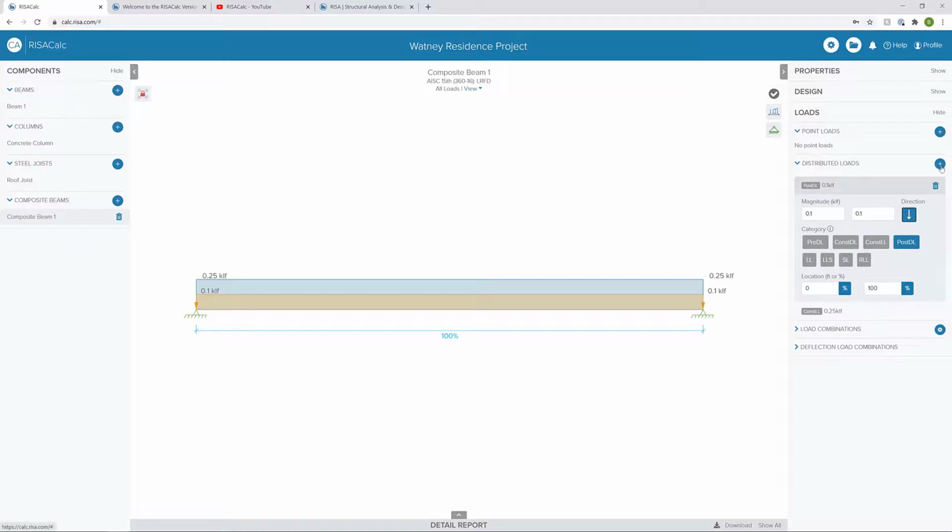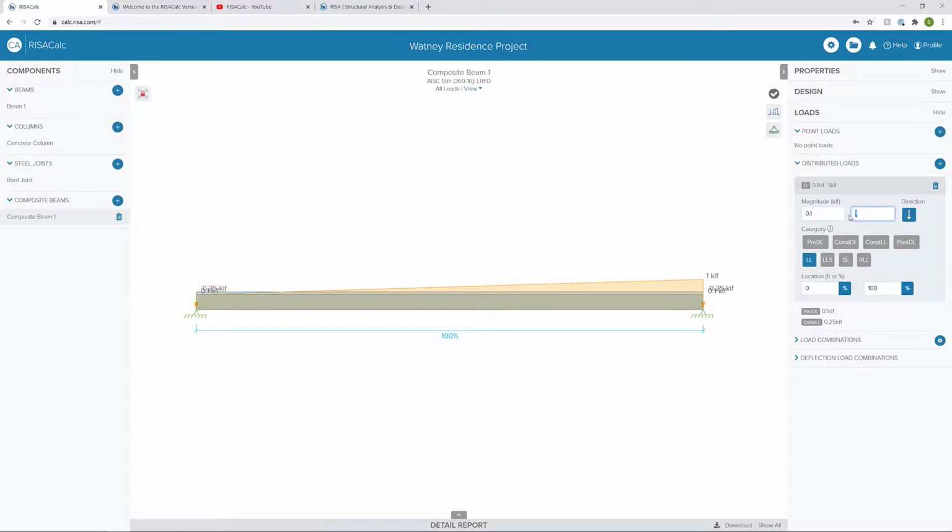Let's go ahead and I'm going to add 2 more distributed loads in this case. The first is going to be a live load, and we'll make this again 100 pounds a linear foot. But I don't want this load to be completely along the full length of that 45-foot beam. I'm going to say that's from the 0 to 20-foot condition. So we've got that space there. Maybe we've got a beam where we've got one type of occupancy on one side of the beam or side of the hallway or something, and another occupancy on the other side. So maybe we've got our corridor and then our classroom or something like that, whatever would cause this difference. So that's the first one we want to add.